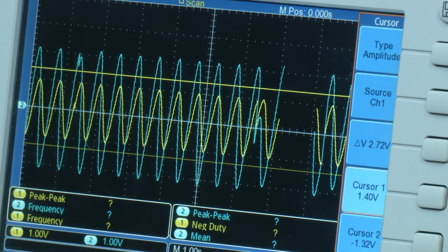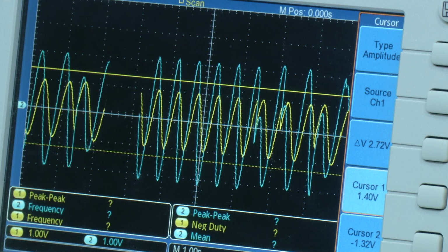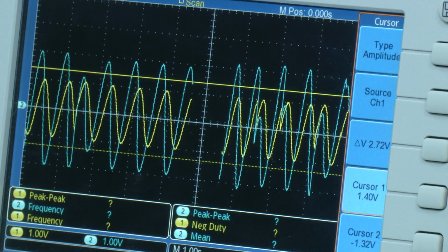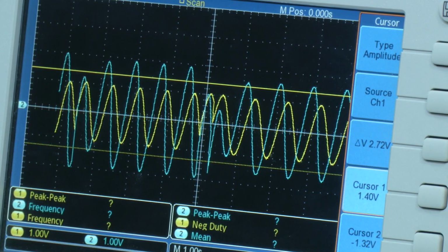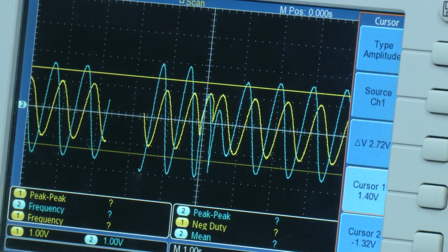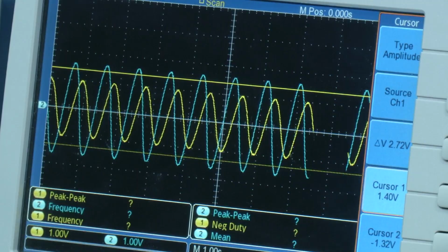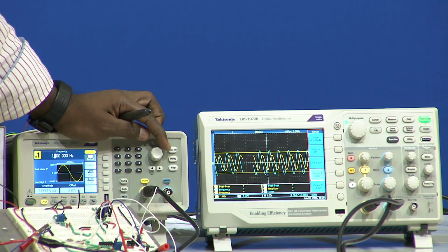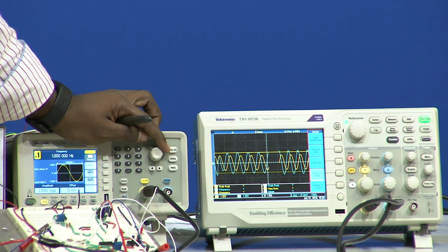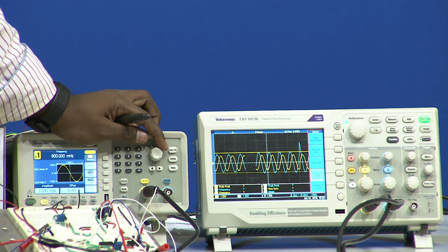So, what I will do is slowly decrease the value. Now, we will observe at what frequency. Right now it is 1.3, right now I am setting it at 1.1. Even at 1.1 hertz, the output is higher than the cutoff value, the cursor point, which is at 1.4. Slowly I will decrease to 1 hertz. Now, suddenly it has moved to the 1.4 volts 3 dB line. Now, I will slowly decrease, and we can see the output is below that cutoff.